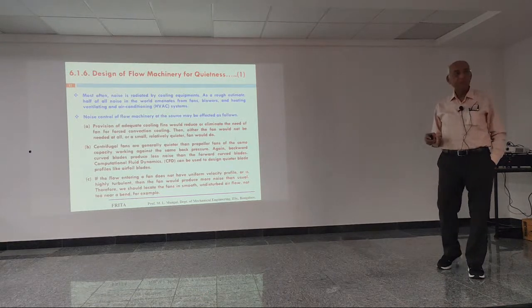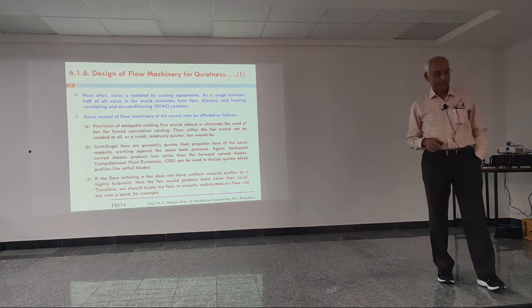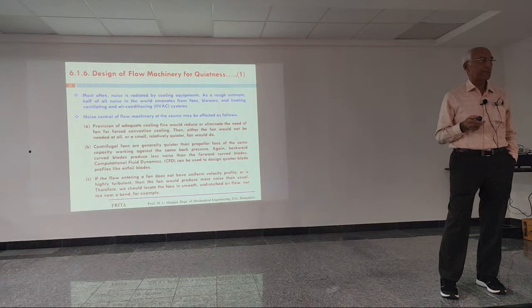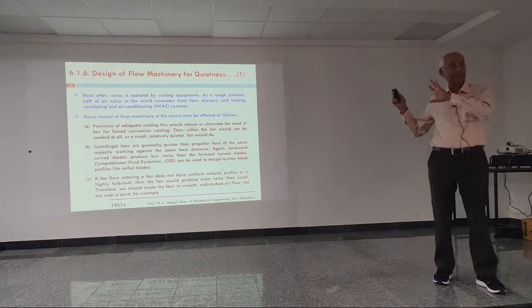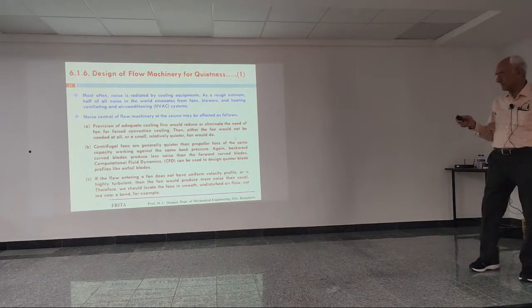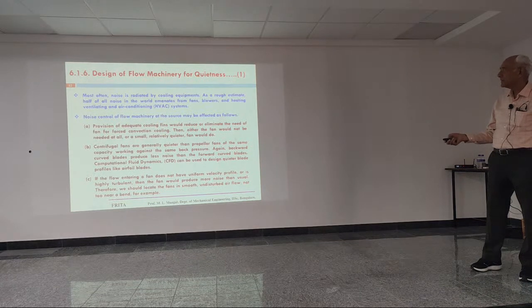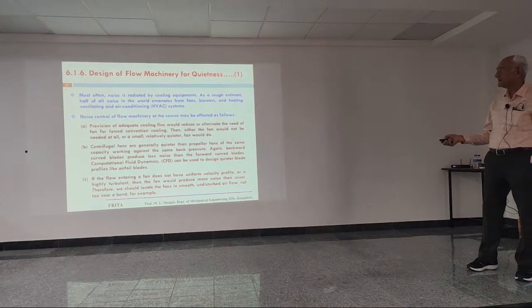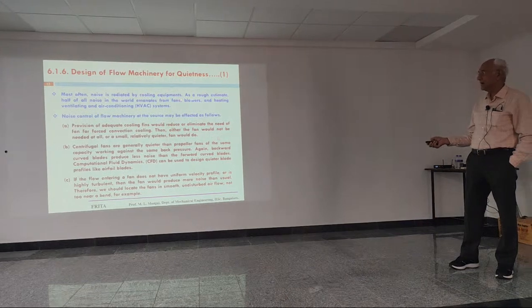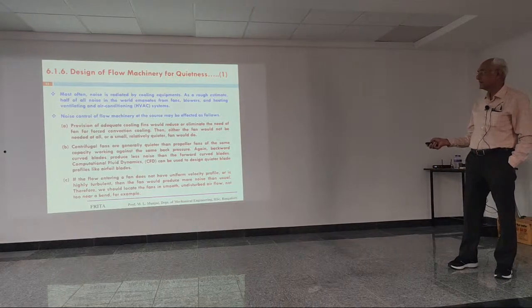Now I was telling you that most of the time noise is from flow machines, and so therefore I am giving you 3 slides only on flow machinery, and they are very important. Please look at the bold text. Most often, noise is radiated by cooling equipment. As a rough estimate, half of all noise in the world emanates from fans, blowers, and heating, ventilation, and air conditioning systems.